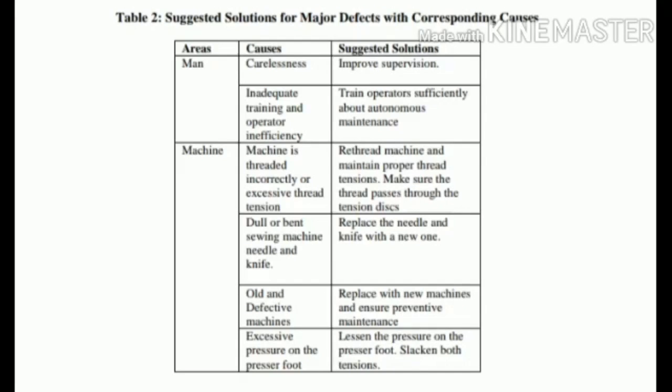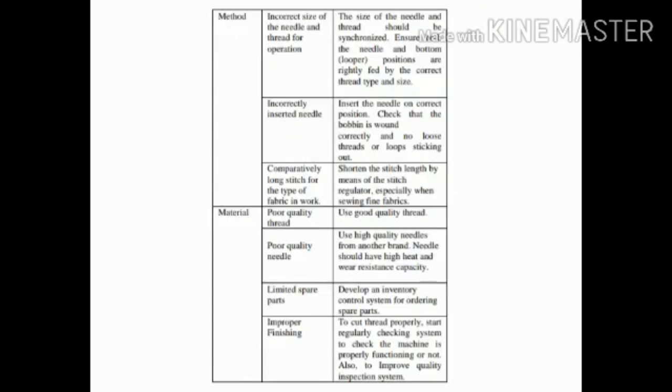Cause: excessive pressure on the pressure foot. Solution: lessen the pressure on the pressure foot, slacken both tensions. Another area of defects is the method.